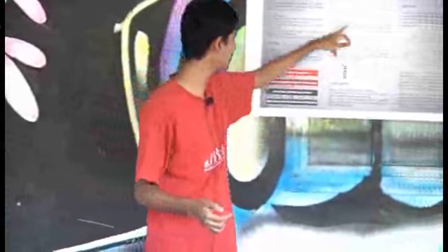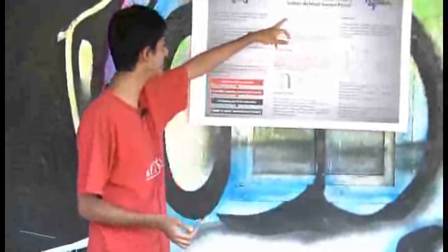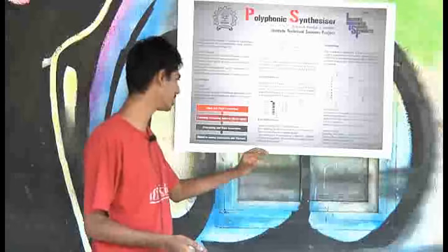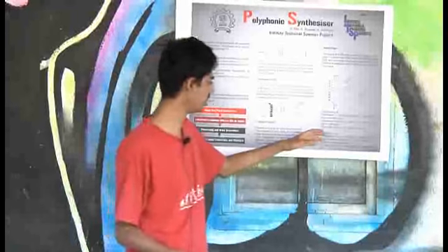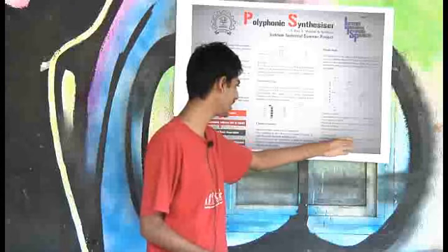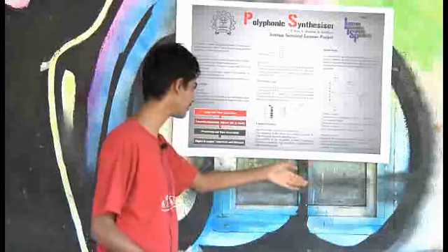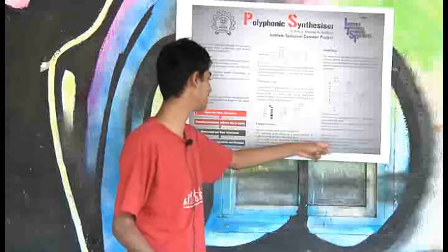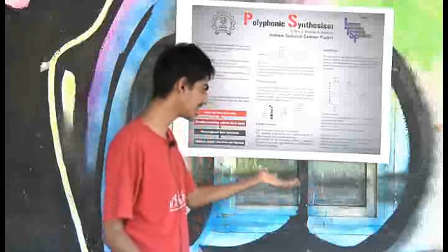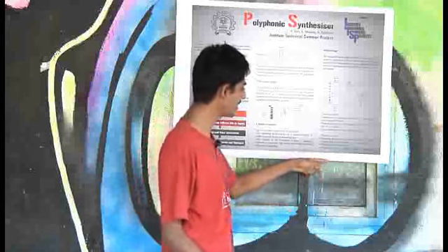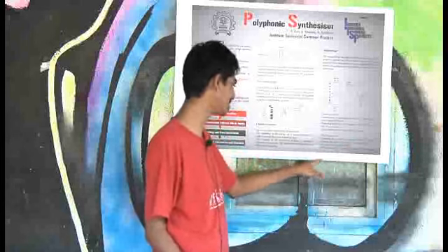However, our input system is capable of easily generalizing itself to holding many more keys, up to 20 or 30 keys. So if anyone is interested enough, he can easily incorporate more keys by replicating the circuitry. And as I said, this noise was not completely eradicated, and so effective debouncing of the keys is one aspect which can be looked into. And the last piece is including circuitry to enable choosing of the instrumental patch.